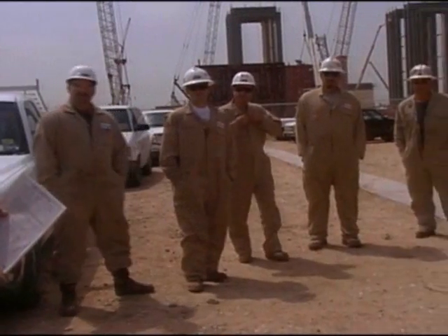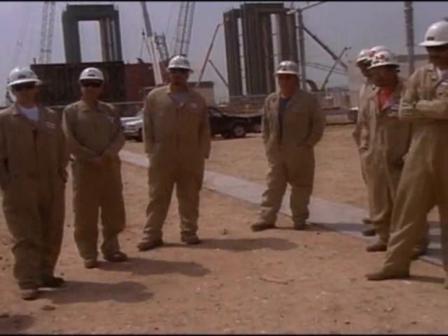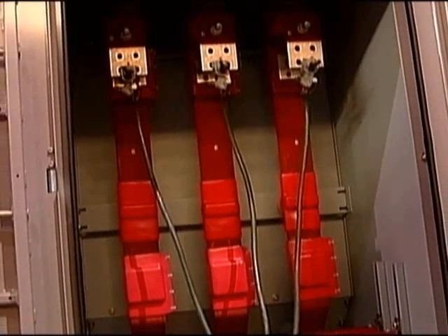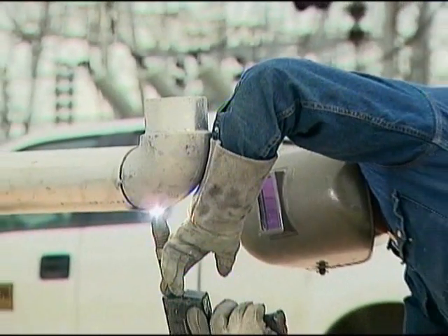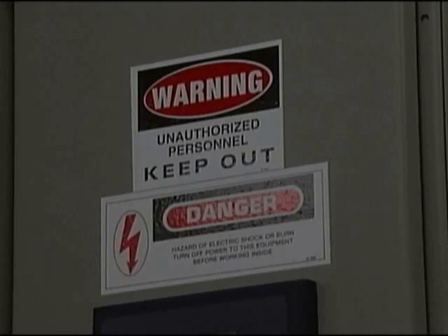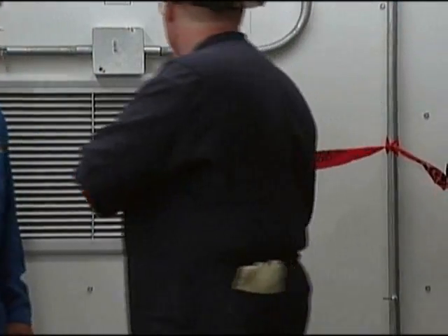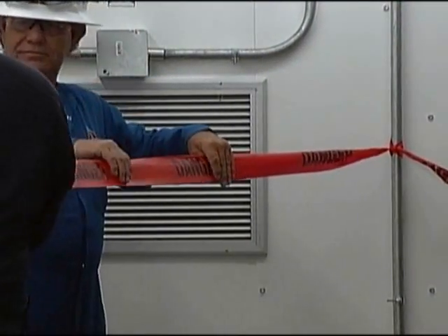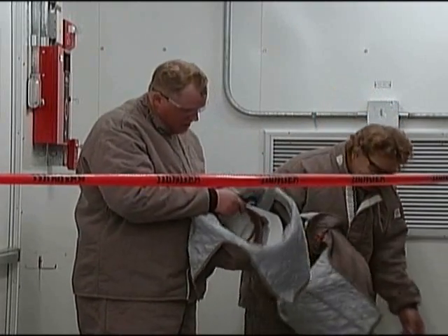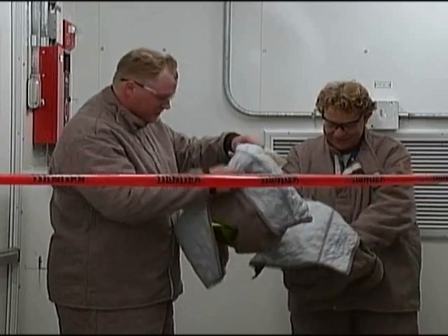Unqualified persons are not permitted to enter spaces containing live parts unless the electrical conductors and equipment involved are in an electrically safe condition. Unqualified persons working close to the limited approach boundary must be advised of the electrical hazards and warned to stay outside the boundary. Unqualified persons can enter with the escort of a qualified person as long as they are advised of the electrical hazards.